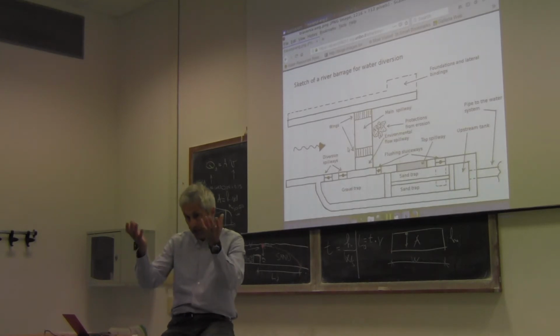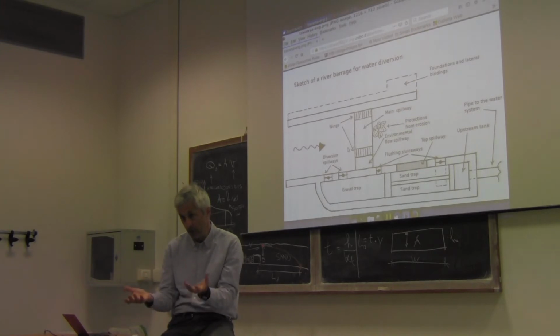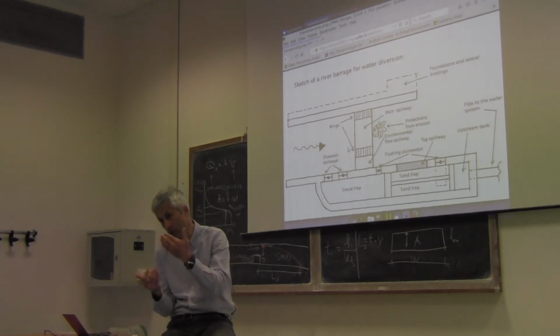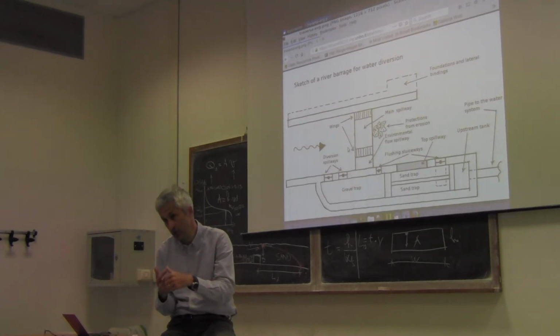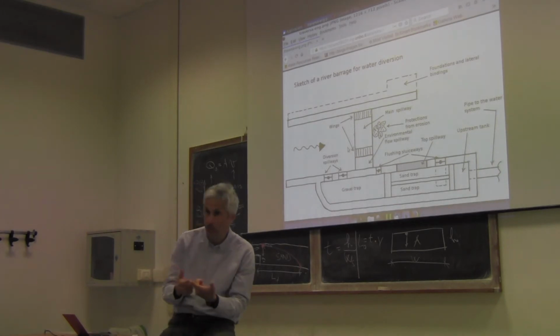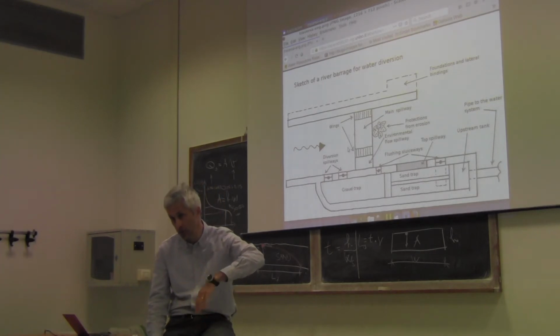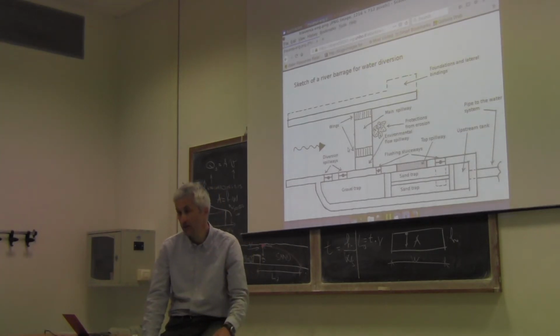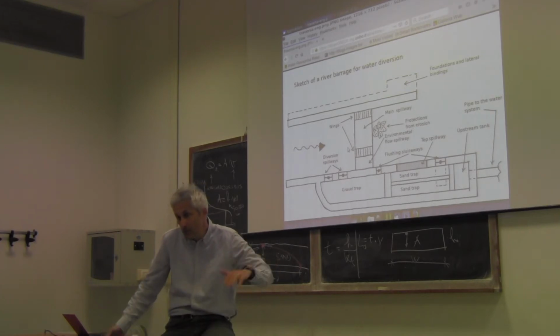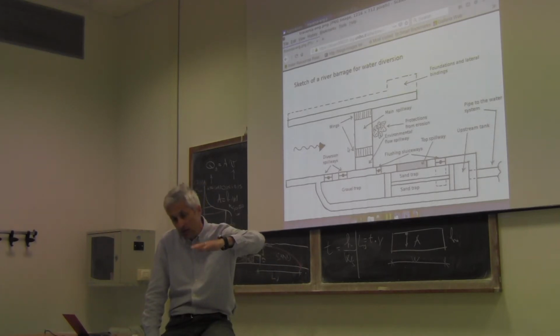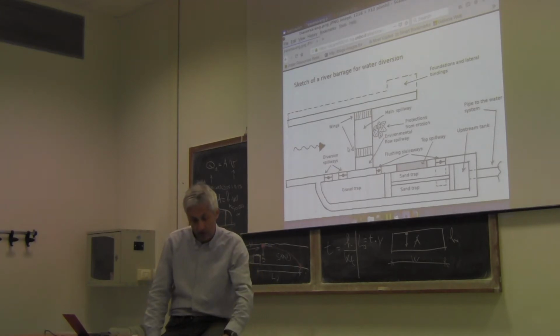If you lower the elevation of water, you are decreasing the potential energy, which is transformed into other forms of energy. It can be pressure or it can be velocity. And therefore, if you cannot increase pressure and you lower the elevation because you make a steep channel, you have an increase of velocity. This is very intuitive. If you build a channel and you increase the slope, you have faster velocity.